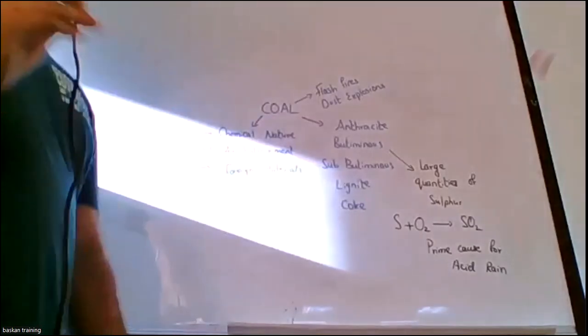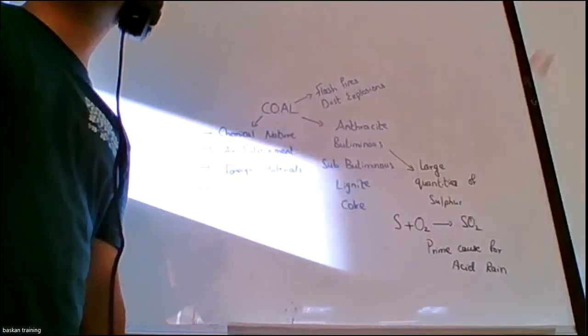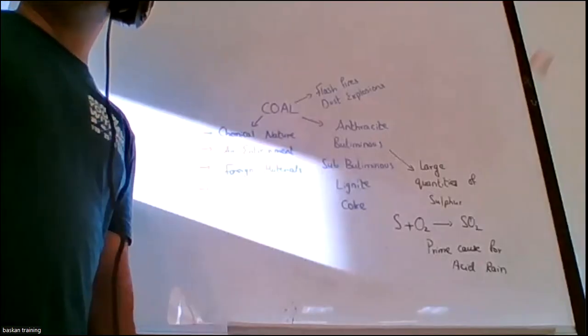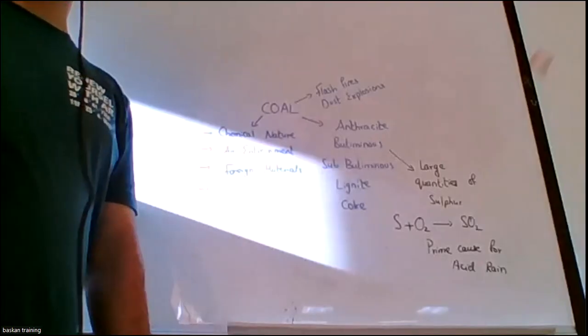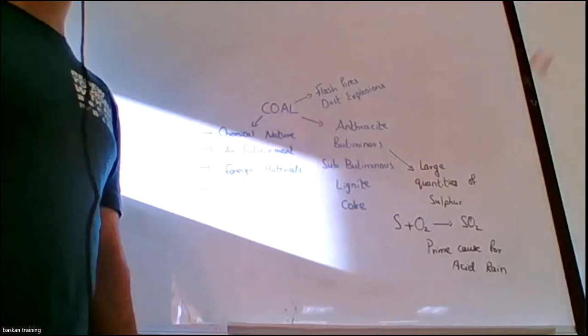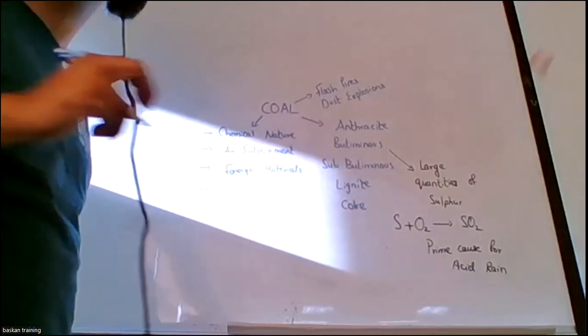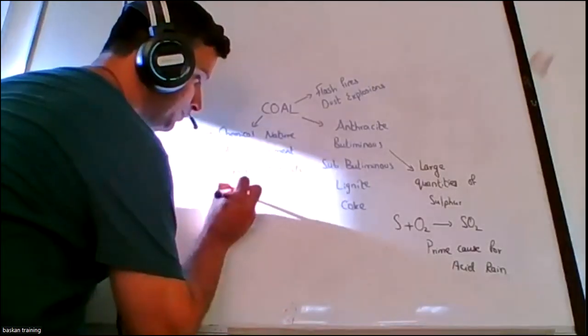Then the moisture. If the moisture is accumulated in the coal silo, what will happen? That moisture accelerates the oxidation process. So heat generating capacities will differ, which will actually start a heating process. Okay, so moisture accumulation.